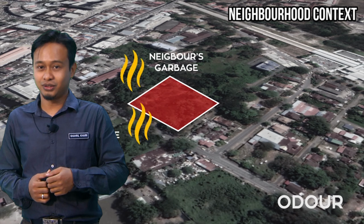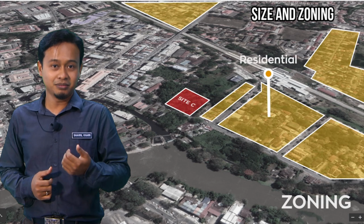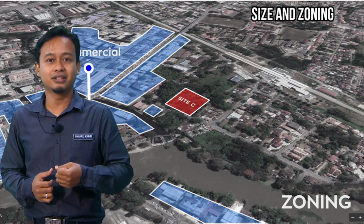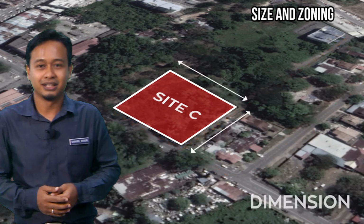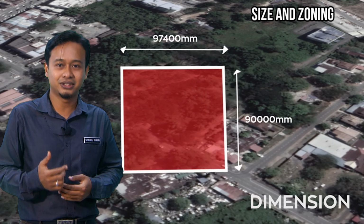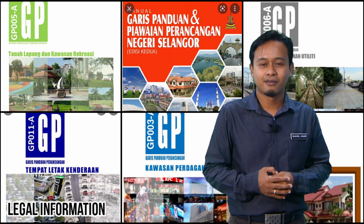Then, we need to obtain zoning plans or documents. Determine the zone of the site under local authorities and the allowance of restriction for development and building under this zoning. Later, we can determine the size, dimensions, angle, shape and proportion of the site.